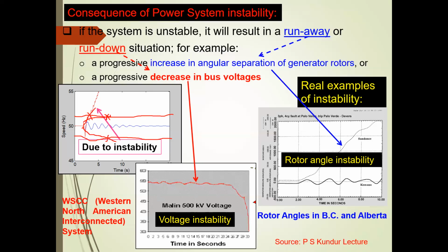So in one case the relay will trip in 2 seconds or less, but in another case the relay will trip after 4 or 5 seconds. It depends upon how the profile of the frequency changes, and when it crosses the upper or lower limits. It is not that at this instant of time the disturbance takes place, and after that much time the relay will operate. No, it is not that way. It is based on sensing the frequency deviation.